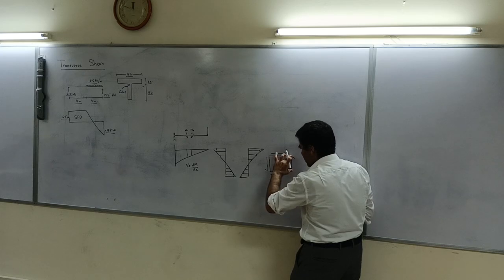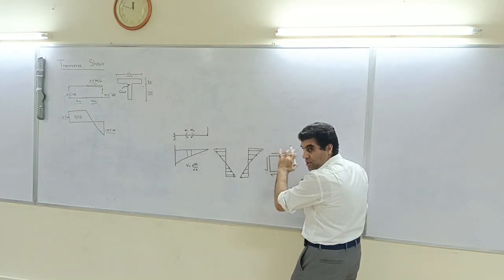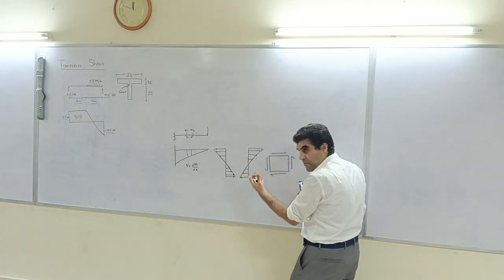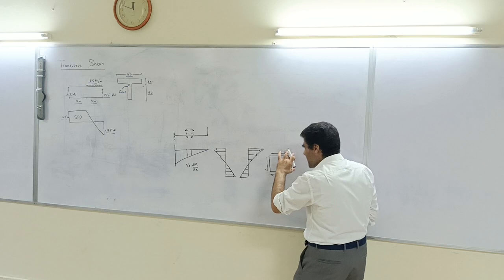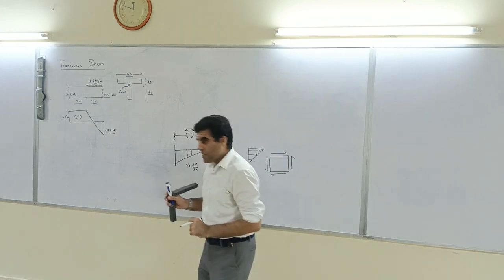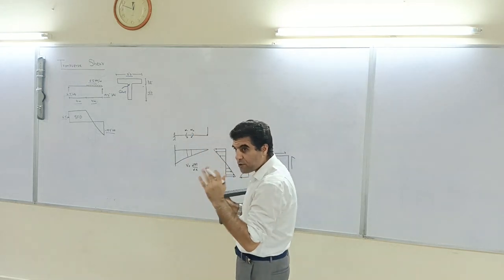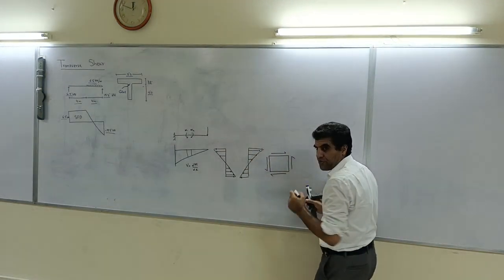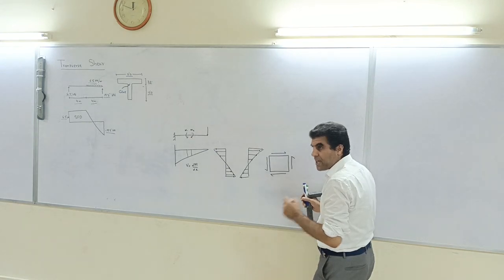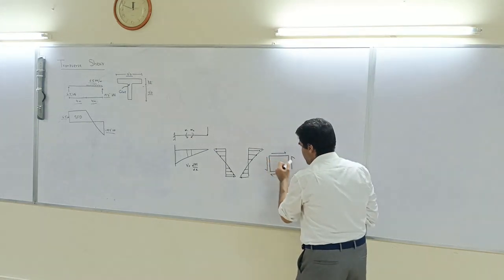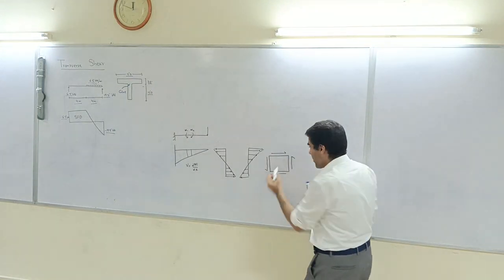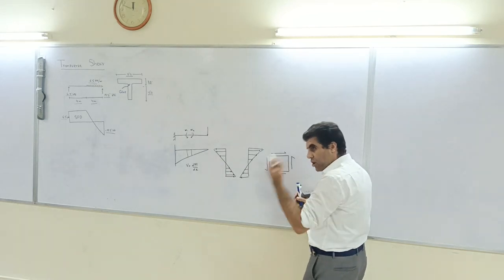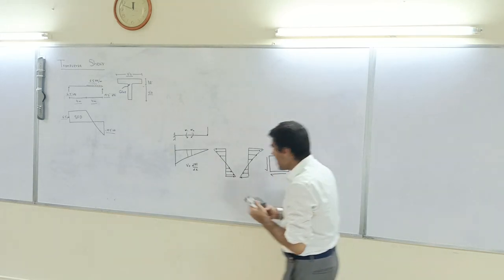From there we get the vertical shear force. So the vertical shear force you get from equilibrium satisfaction, and this is the same vertical shear force that the shear force diagram gives us when we draw it. So in other words, the horizontal shear force is equal to the vertical shear force if we assume that this is a square box of very small magnitude. So the horizontal and vertical shears are equal.